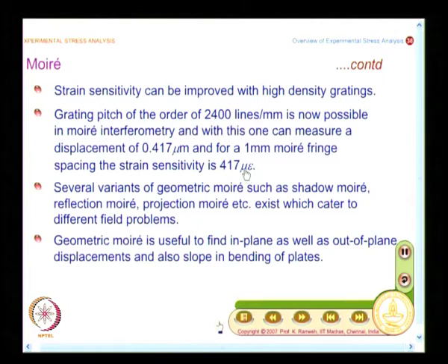It is still large, because I said we live much below 2000 micro strain for most of our practical requirements, and we may operate around 500 micro strain for many of our strategically important components.